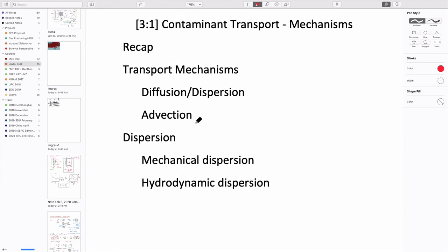So now you should make a mental break between two different fluids flowing, maybe water invading the vadose zone, an air-filled porous medium, and establishing an equilibrium with some water and some air, or a saturated groundwater zone being invaded by a NAPL and establishing an equilibrium with lenses of that NAPL and the chimneys of the NAPL in relatively low saturations.